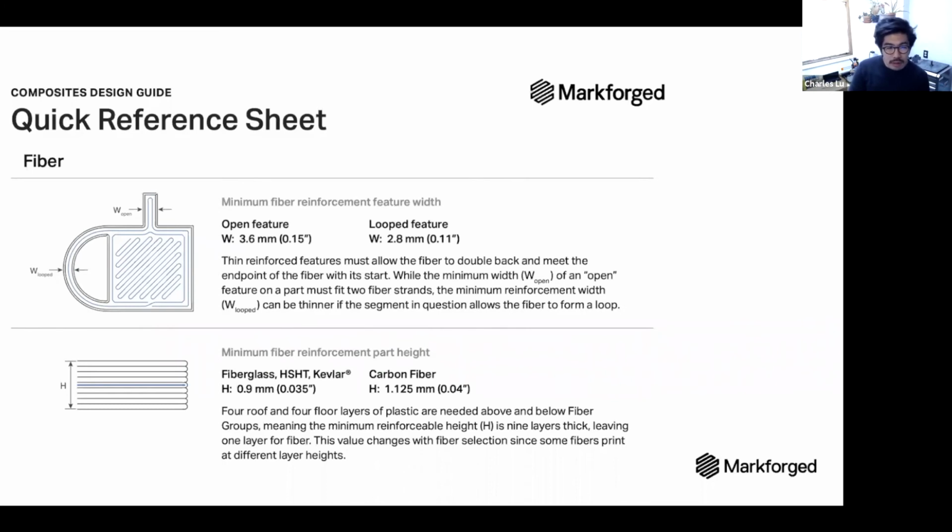Tim, I see your question here about FEA data for continuous carbon fiber. We don't have it yet, but it's in progress. I think we're going to have some eventual API linking with MSC, I think, is our first integrator that's going to build into our API and have an FEA format come out, but I would look forward to that sometime later in the year. It is not something that we can do right now, but if you wanted to just estimate based on 1 millimeter per path of fiber, I think that gets you pretty close.